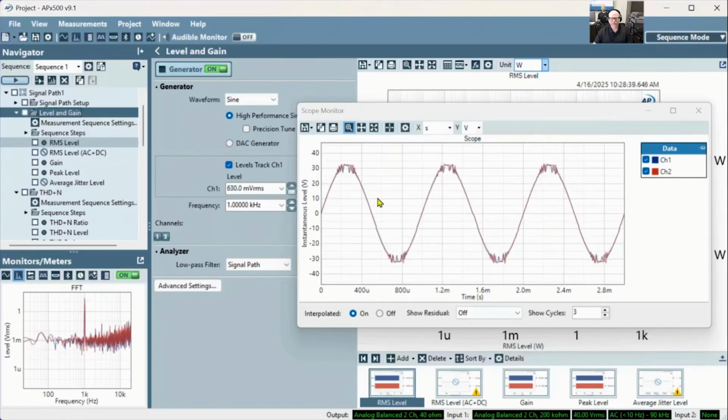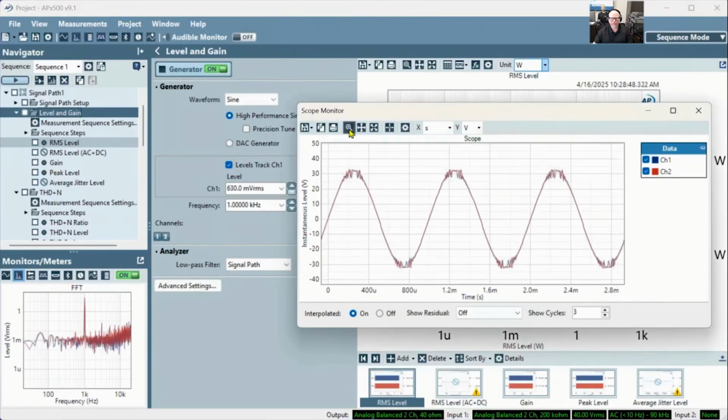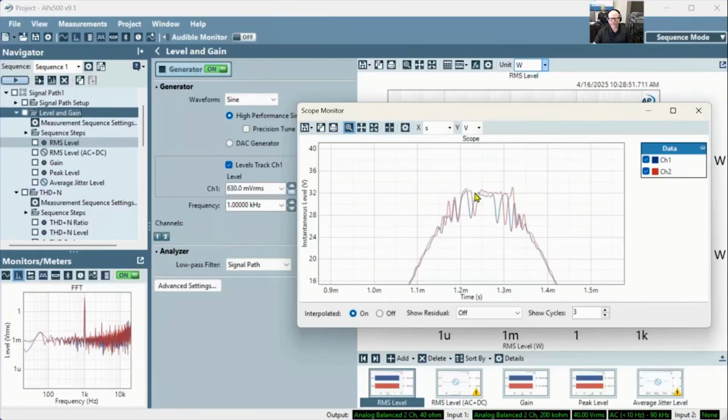And you'll notice that at a certain point, it starts to clip. The reason people use that clipping term is we look at the peak of our waveform, and what's happening here is it's actually running into the maximum voltage of the power rail supplying the amplifier, and the peak of our sine wave gets flattened out.